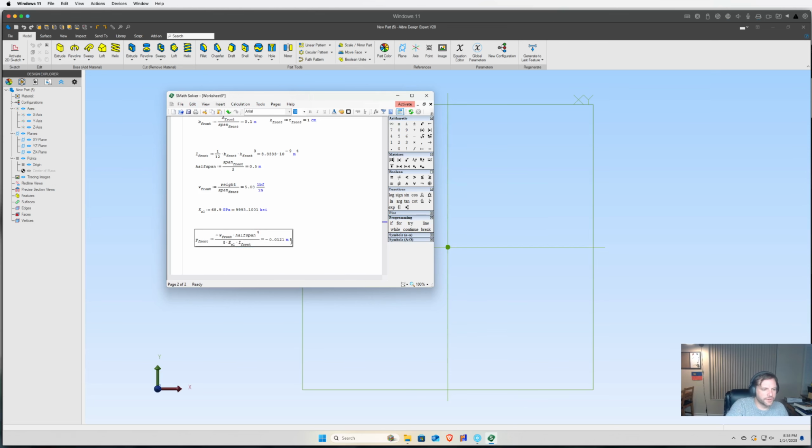All right, so that tells me right there, we get a deflection of the wingtip, effectively. We're expecting it in inches. Ooh, so we get about half an inch of deflection at the wingtip from that load.